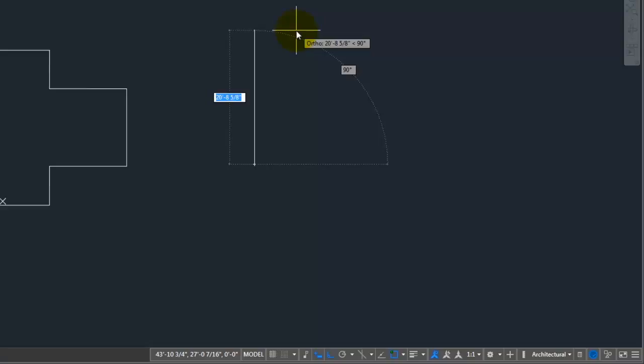So a lot of times people leave dynamic input on because it's an easier way of interacting. You don't have to keep track of the coordinates in your head. I like to point out the coordinates because sometimes if you were doing an angled line or something, it makes life a little bit easier. But we can work with the dynamic input for the most part.